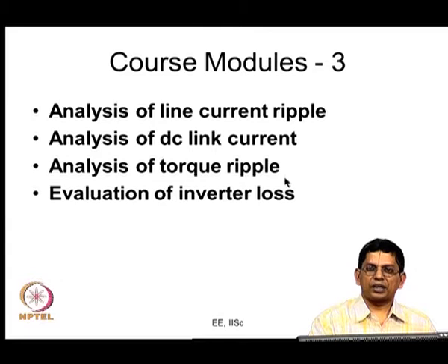We tried to look at the 6th harmonic torque, and how you could evaluate specific harmonic torques like 6th, 12th, etc. And we also looked at the possibility of eliminating something like the 6th harmonic torque or the 12th harmonic torque by appropriately selecting the switching angles.